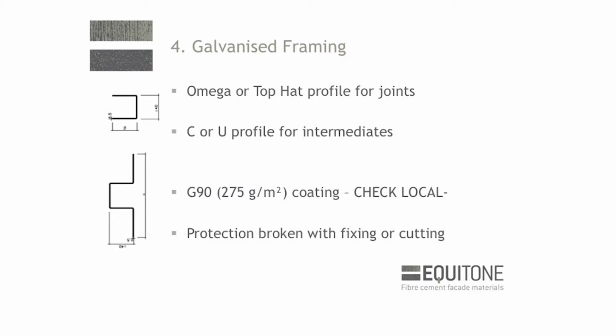Now, what I will say to you guys is that if you are using galvanized frames, what happens sometimes is, when you drill the hole in the frame for the rivet and you get the little debris and the filings off of it, if they're left in the hole, what can happen is that when it rains, under heavy rain, there can be little drops of moisture around the hole, and then we'll get a phone call. Your panels are rusting. Impossible, there's no metal in them. Well, they're rusting. I have brown streaks running down under every fixing.